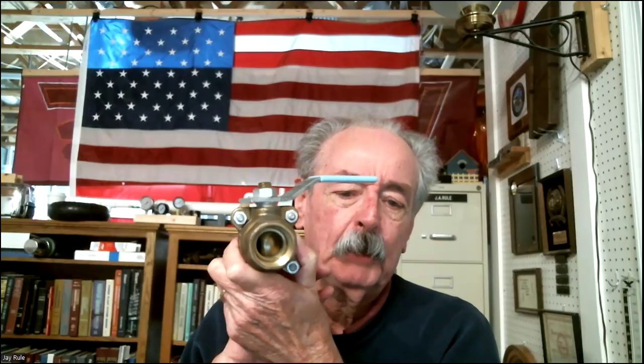So if we're coming in here at, let's say, P3, and coming out here at P4, P4 is going to be much lower than P3, and the mass flow rate is going to be dramatically reduced from the wide open position. So you get the idea that the smaller the effective opening of the valve, the higher the pressure drop, and the more restricted, the more throttled the flow is.